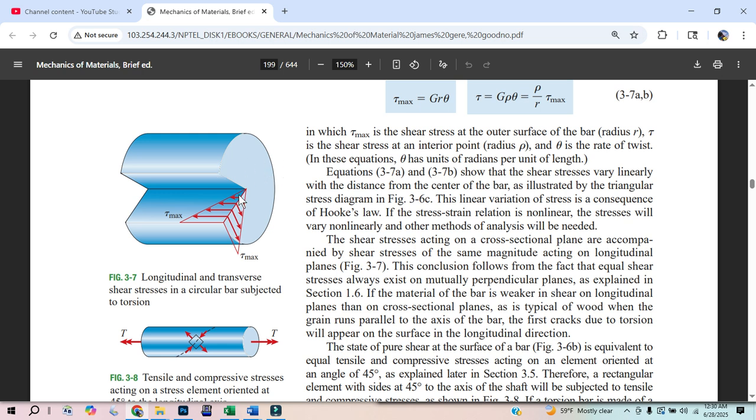And what we did there is just like, well, maybe I want to know what the radians is. Well, that's going to be arc length divided by the radius. So arc length divided by r. And in this case, maybe I just know the angle of twist. Well, that's the angle of twist divided by 360 times the circumference, and that'll give me the circumferential distance.